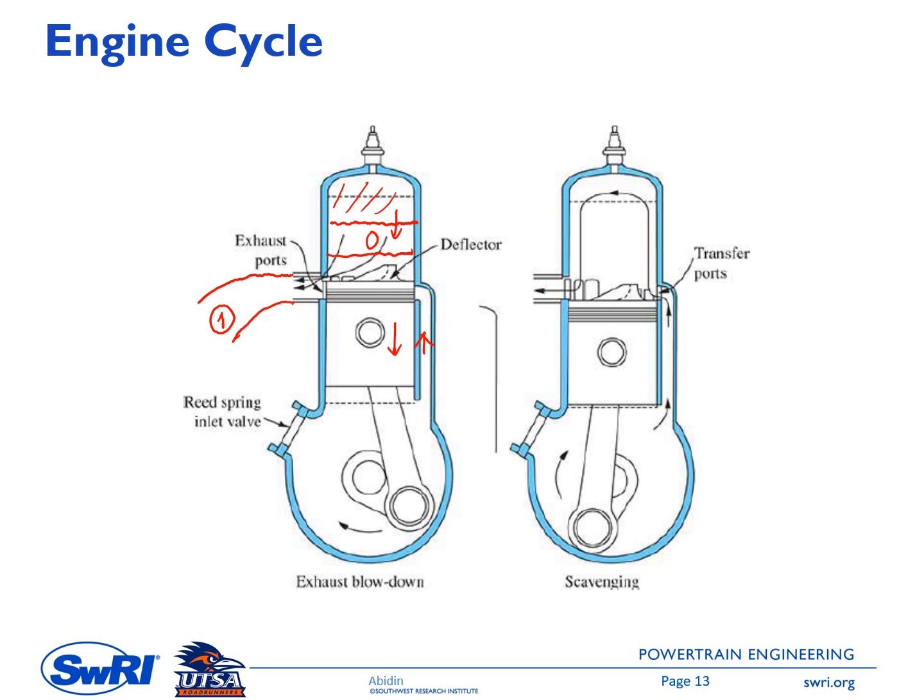And then the piston continues to move down toward bottom center, and at some point the transfer port will also open, and because the crankcase pressure, let me put here number 2, is higher than the chamber pressure, 0 here, there will be a mixture flow. It can be just air, or air plus EGR, or air plus EGR plus fuel if it is a spark ignited engine.